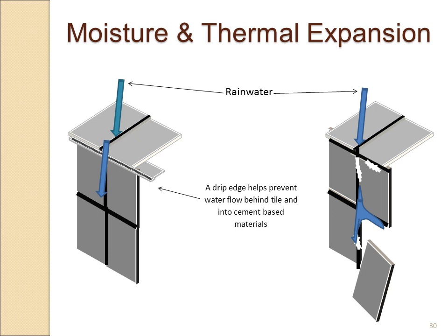Well, what we've noticed is a rash of installations where there's been no moisture or very little moisture in the assembly. And now all of a sudden, with all the rain and all the moisture, it's caused some substantial thermal expansion. And as you can see from the picture here, we're seeing a condition where drip edges were not installed properly. Water's getting behind the system, and that water's causing a great amount of thermal expansion. And we are literally seeing tiles fall off the building.